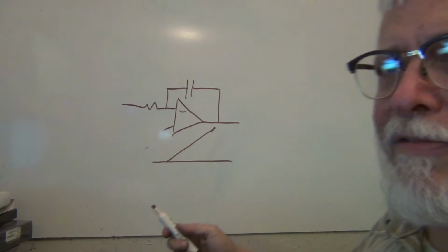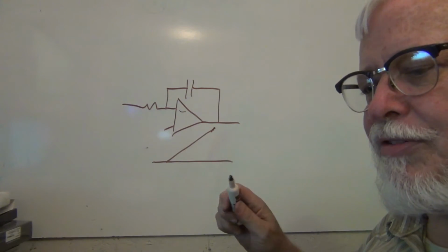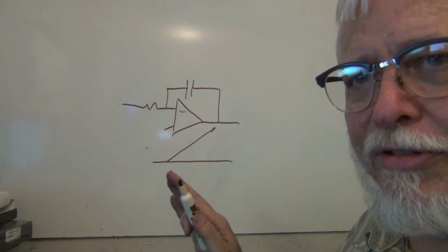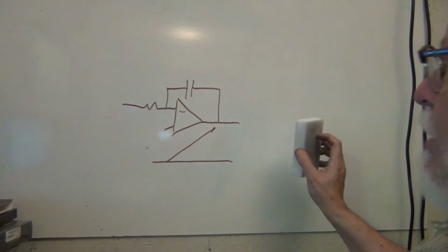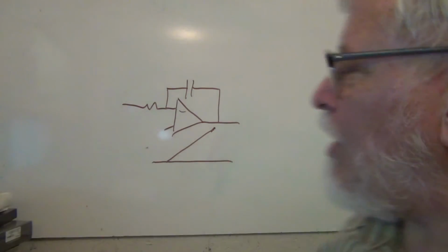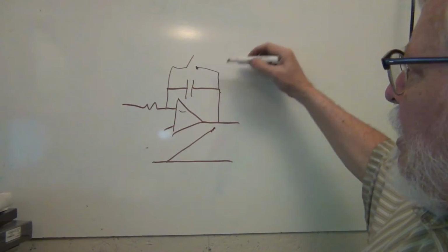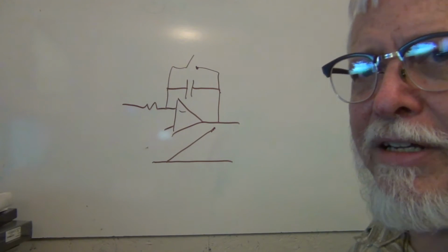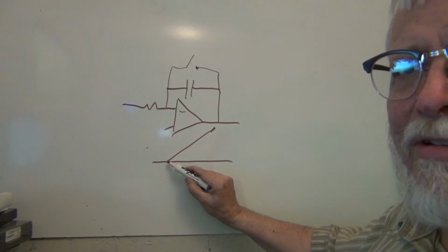Okay, now there are several special ramp generators that the Scanimate uses that have to do with creating a raster. We'll talk about that in just a moment. Okay, so that's a ramp generator, and most often the ramp generator is started by an external event. So if this switch is closed, the ramp gets held at 0.